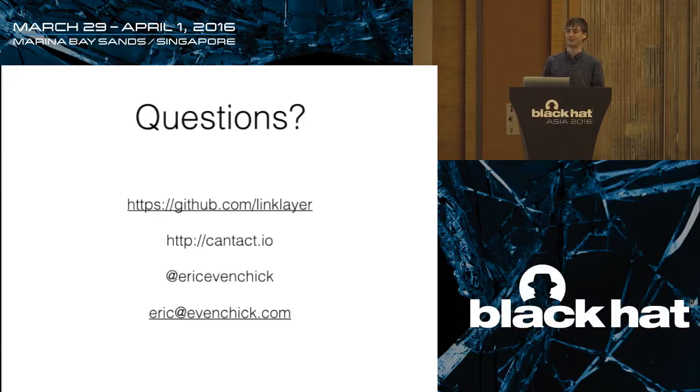Of course, someone can always smash the window of a car. That's an assumption you kind of have to make. I like to say that the oldest denial of service attack on cars is slashing the tires. It's pretty effective. But physical security, at least for CAN, is going to start to matter when you see the risks for it. In terms of the devices themselves, you can pot them, you can do all sorts of things, but don't assume that no one can remove it, because every time that assumption is made, it's proven wrong. There are hundreds of examples of devices that said, oh well, no one will be able to get inside of our device. And it turns out with enough time and enough hot air guns, you can remove most potting.